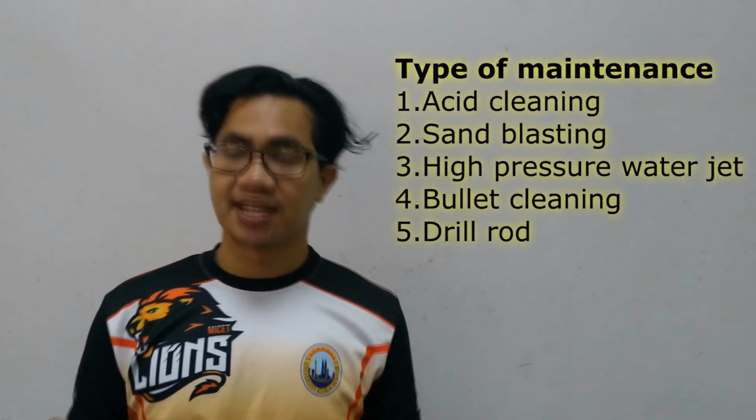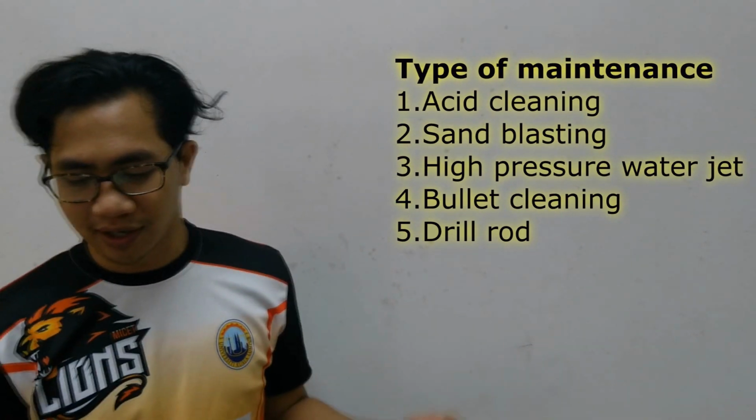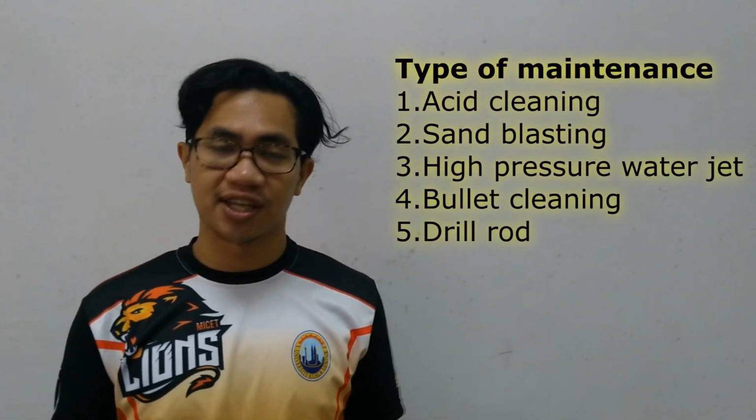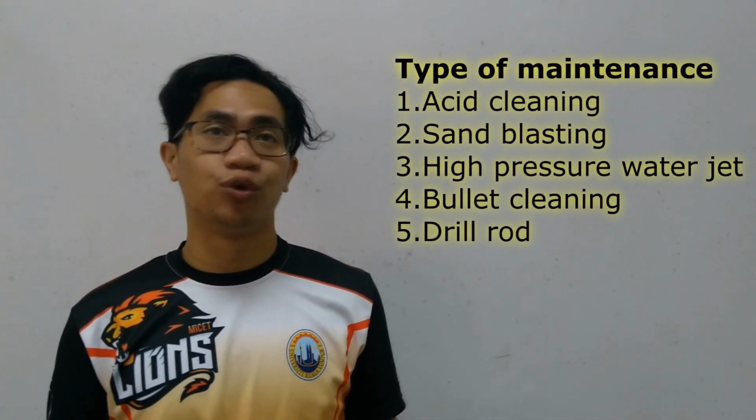One of the types of heat exchanger is the turbulent heat exchanger, which we can clean by acid cleaning, sandblasting, high pressure water jet, bullet cleaning, and drill rod.